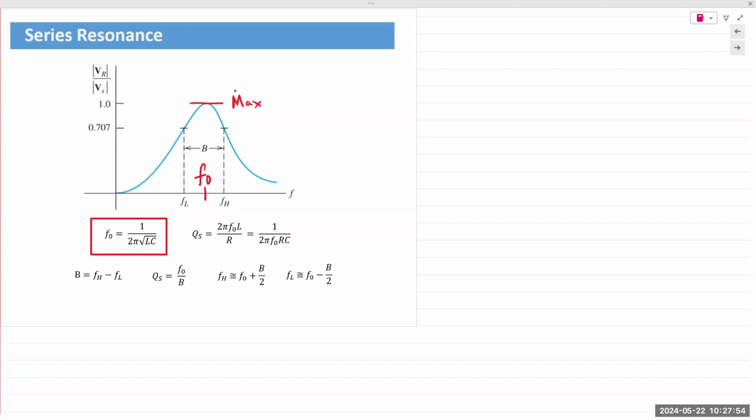So typically, instead of using a resonant circuit, they would use simply a low pass RC filter and a high pass RC filter. They would use resistors and capacitors for both high pass and low pass, and you combine them together, and it becomes a band pass. So it always comes down to money. Always comes down to money. If you use an inductor in a circuit, it becomes more expensive.